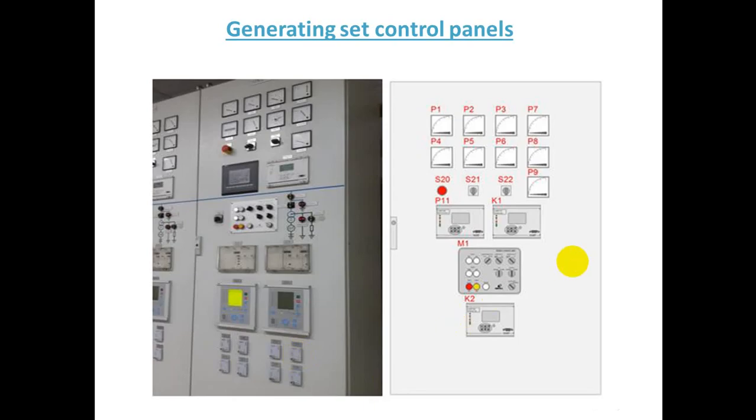The control unit of the generating set consists of the control panels in all of the power plants or power stations. What are these and what are they used for? The control cabinet for the control of the generating set contains equipment for output monitoring and synchronization, and generator protection, as well as a manual control unit.